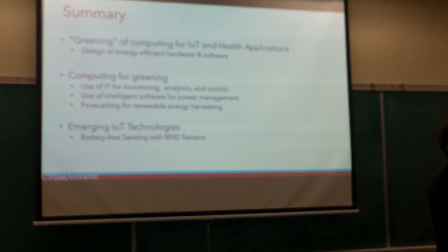Because the RFID reader probably consumes 4 or 5 orders of magnitude more power than a tag. If you were to leave that RFID reader running all the time, you would need thousands of RFID tags in order to drive the average power consumption down. We built that as a research project, so we didn't do any duty cycling of the light bulb itself, but you could think of using another proximity sensor or motion sensor to trigger turning on the RFID reader, using some other low power sensor.